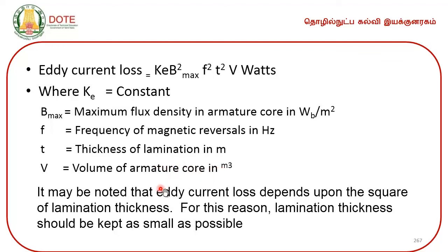It may be noted that the eddy current loss depends upon the square of lamination thickness. For this reason, the lamination thickness should be kept as small as possible.